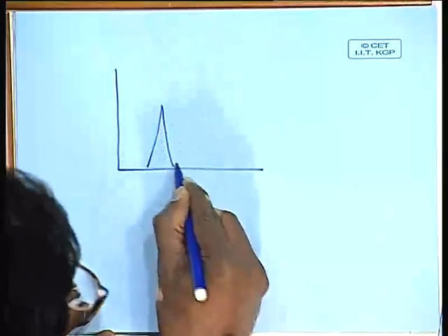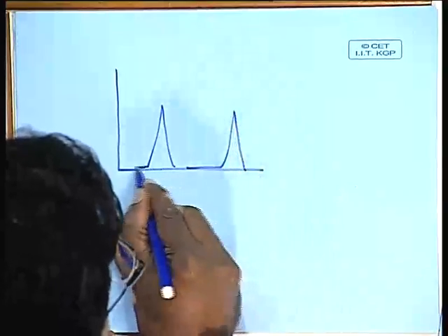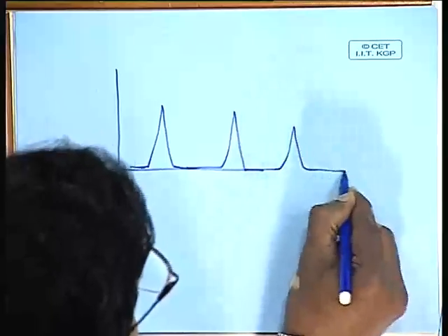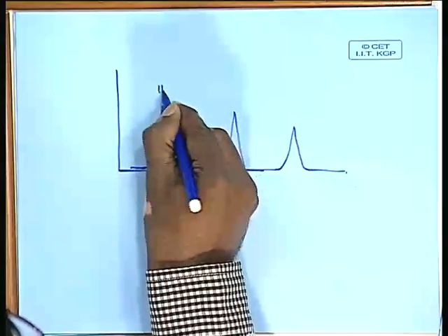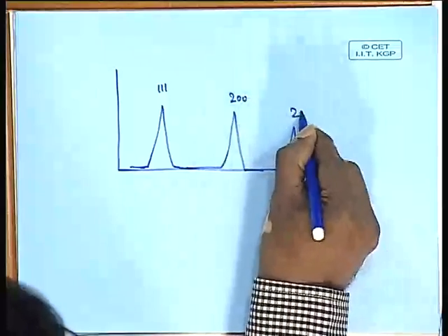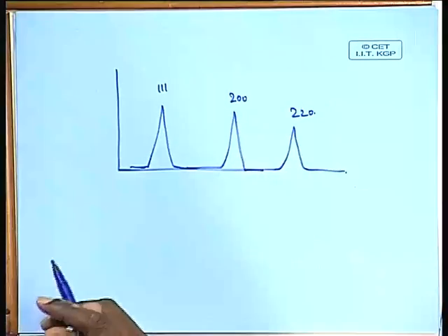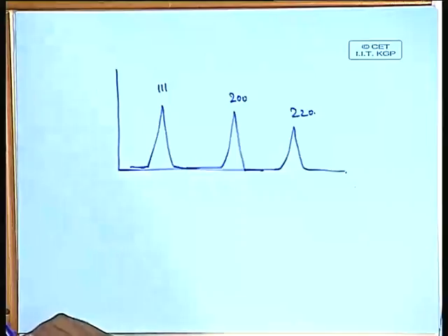And what did he observe? He observed that you have one phase. He had taken a eutectic, did an X-ray diffraction, and he gets peaks which are just the normal peaks of this type, one corresponding to 111, another 200, another 220. This is what you get if you have a silver copper solid solution. The silver copper solid solution must be FCC, because silver is FCC, copper is FCC, so obviously the solid solution should be FCC, and that is what you see here.